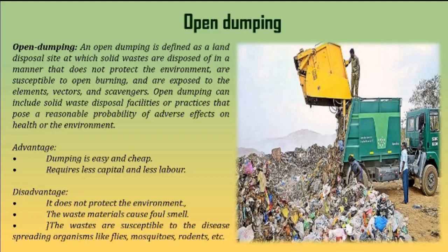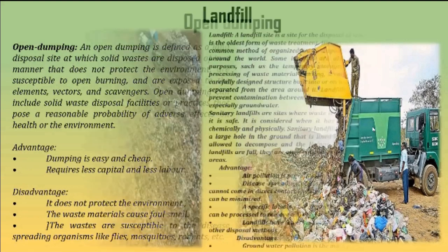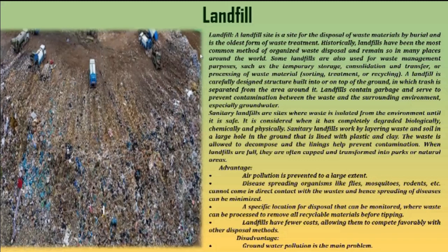Now, what are the disadvantages? Disadvantages will never end, because if you go for the cheap one, it can never be the best one, right? So as the process is cheap, it cannot be the best. It does not protect the environment, it causes foul smell, and the waste is susceptible to disease-spreading organisms like flies, mosquitoes and rodents, right? So open dumping is not preferable, but it is followed in many places because it is very cheap.